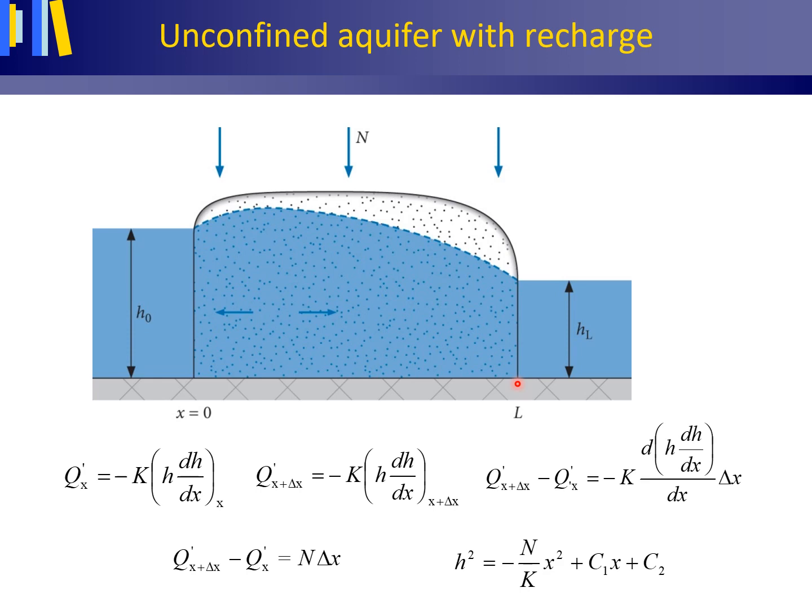Again, and as specified in section M5 at the end of my book, we can set up the water balance, shown here, for a vertical column or rectangle of the aquifer. You can think of this area constituting that rectangle. And then combine this with Darcy's law. You see Darcy's law stated here on the top lines to obtain this equation.